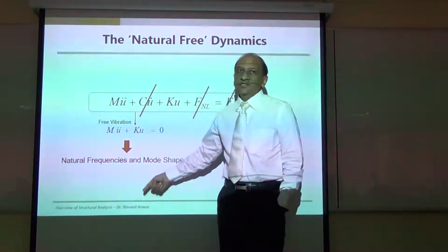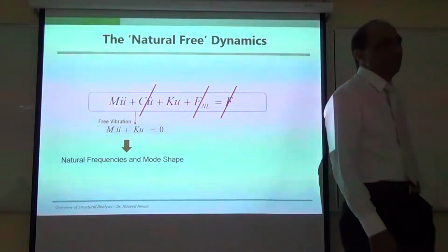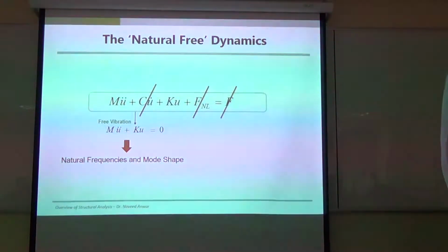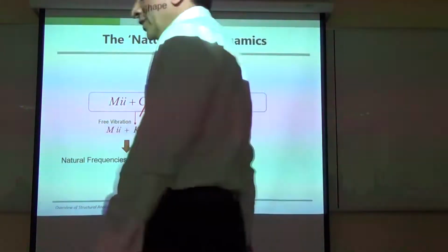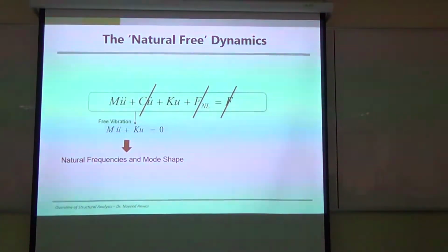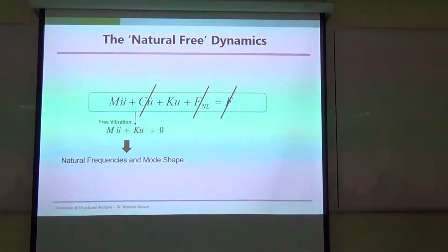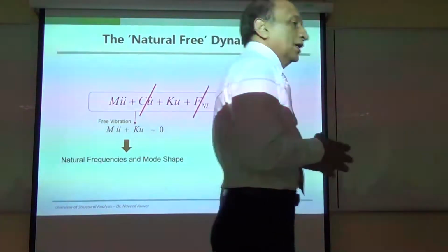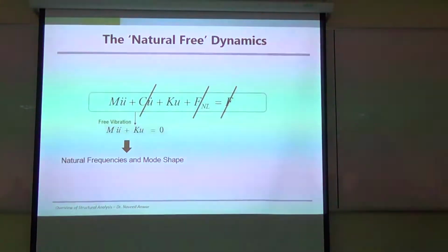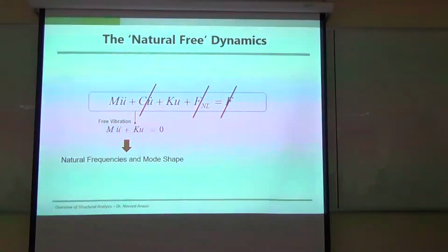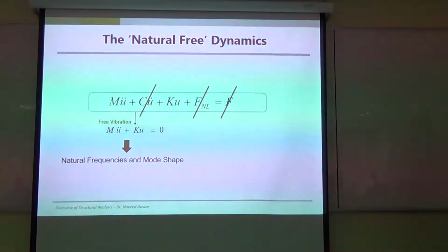So if you are able to understand the meaning of the frequencies and meaning of the mode shapes, you will understand the dynamics of the structure, you will understand the health of the structure, you will understand how it will perform in earthquake, you will understand how it will perform in wind, you will understand how it will perform in moving load, whether it will vibrate. If I'm walking here, will it vibrate or not? If three people are walking here, will the floor vibrate or not? So everything about the structure's response can be predicted if we know these frequencies and mode shape information. That is a starting point for the dynamic response.